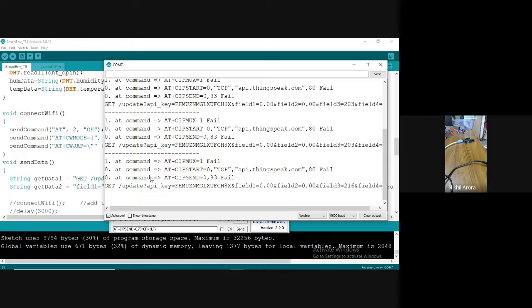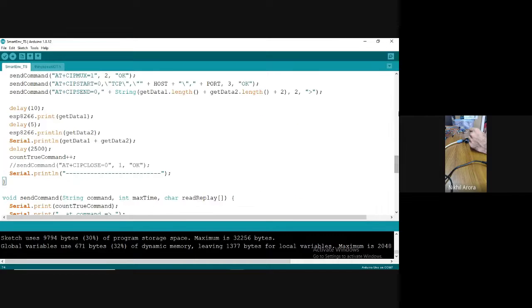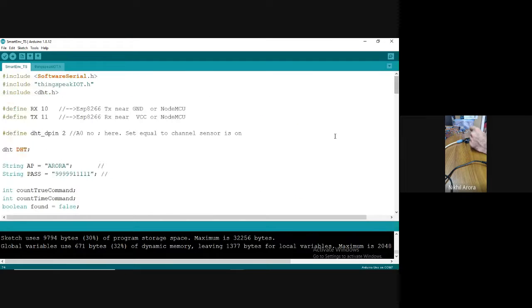So what I want is one green wire to behave as ground. V in nearby is ground. Now pin number 10 is RX. Okay, pin number 10 is RX. 8, 9, 10 is RX. 11 is TX. Over.